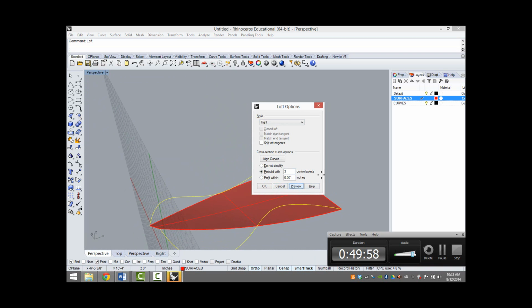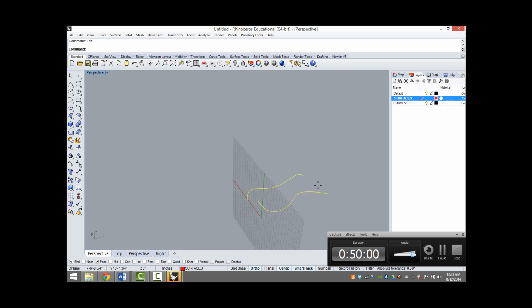So it makes more sense to loft with complicated geometries, or not necessarily curvilinear geometries, but many times those end up being more complicated than orthogonal geometries. I think for the next exercise, it won't be necessary that we loft, but if you want to get used to that workflow, you can use that instead of extrude just as easily. Okay?